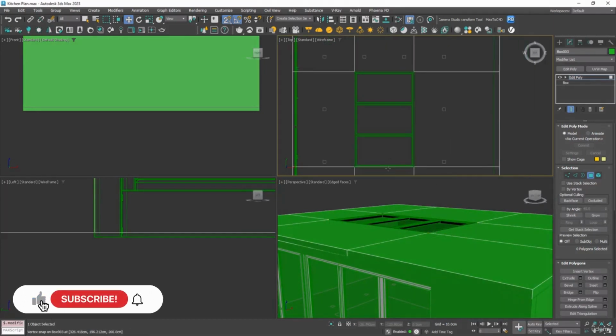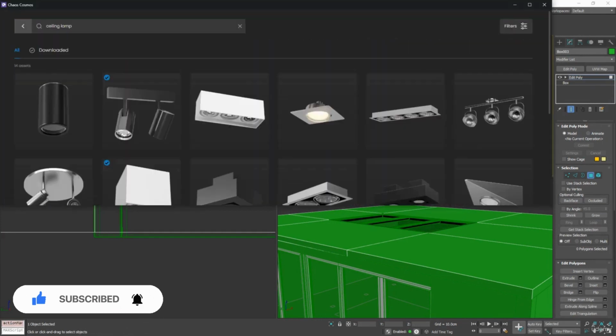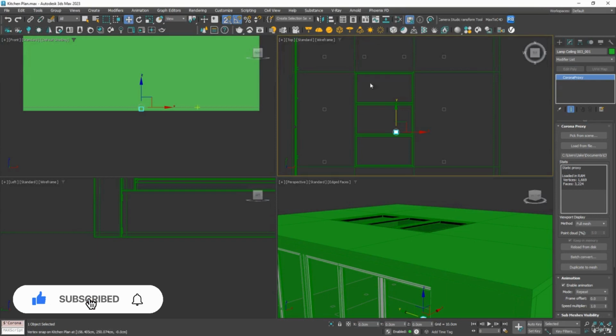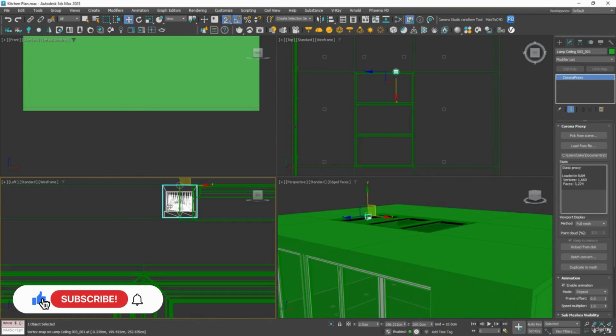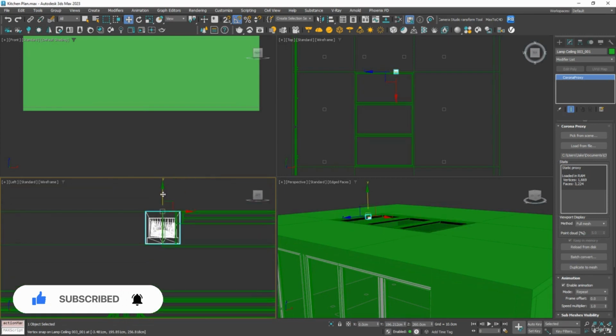All right, next up, let's find some lights from Cosmos. So I'm going to search for ceiling lamp, and let's use these ones. I've already got them downloaded, but you may just need to click in the top right and download them, and let's import them. And in the left view, let's get them positioned. So I don't want them all the way up here, I want them to slightly overhang. So I'm going to turn off snaps by pressing S and just have them overhang a little bit.